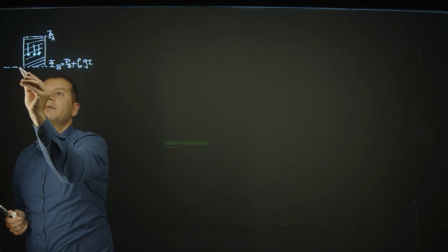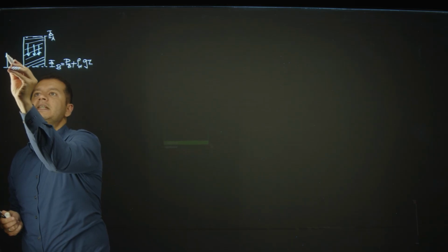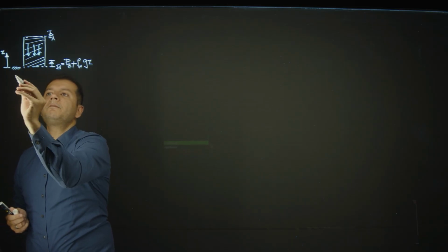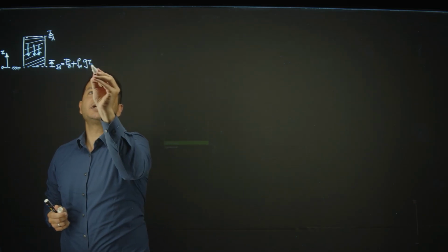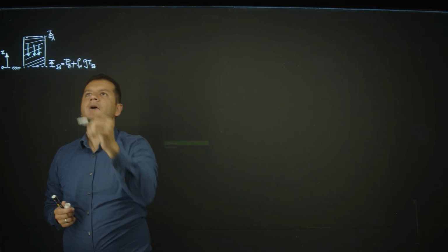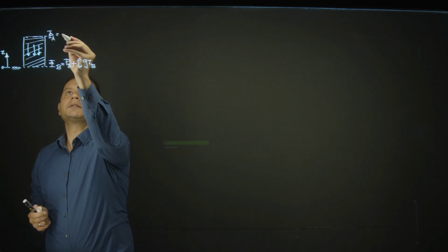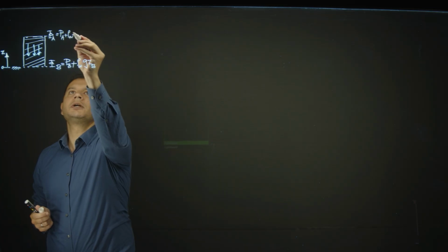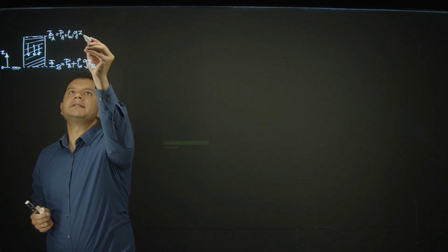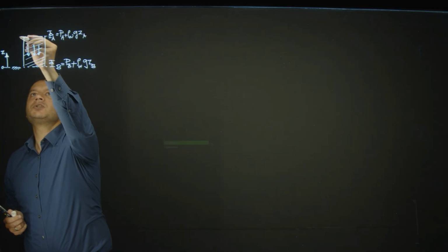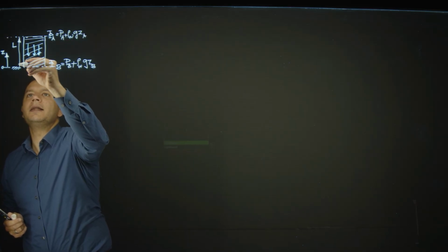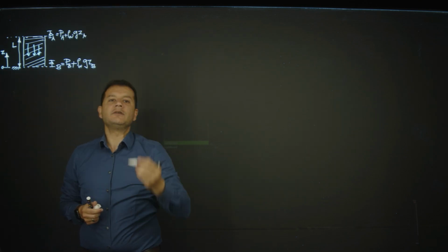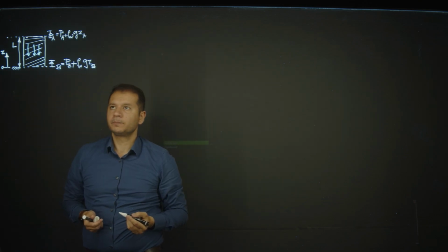So we take the bottom of the sample as the reference for Z, which is going upward, and it starts from 0 here. So Z at location B will be 0. Potential at the top is pressure at the top, A, plus density of water, gravity, and Z at A. Imagine the sample has the size, length of L. So ZA would be L in this case.